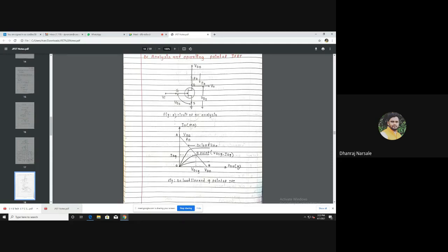So what we are going to do is, first draw the drain characteristic or VI characteristics of JFET. For example, I have drawn this first curve. For the first curve, how did we draw it? The voltage between drain and source is VDS, so VDS versus ID. If you take the readings for the different values of VDS with the value of VGS constant, and we are measuring the drain current ID, and we will plot the different points. For example, I have taken 15 readings for the value of VGS equal to 0, and by varying the value of VDS, I have taken the 15 readings. For those 15 readings, I will get the 15 points in this way, and if you connect those points, then I will get curve number 1.